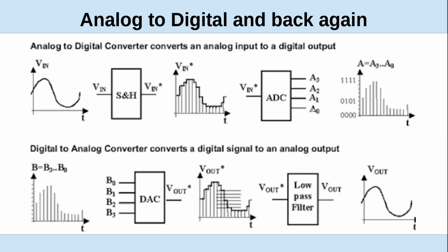So you still have just an amplitude in the bits, and then your clock is going to do the frequency or the sampling rate? Yes, on how fast you sample it. So every sample, like if you're doing an RF waveform, if you're sampling at a gigahertz, let's say, then you get that digital sample, and then you get the next one. So in the SDR, you've got to look at more than one sample to process a filter or something like that. You can't just take a single point.